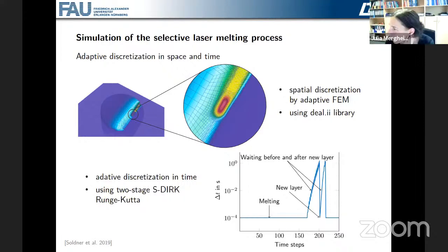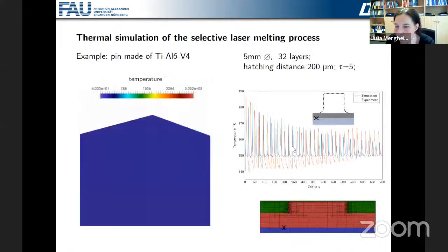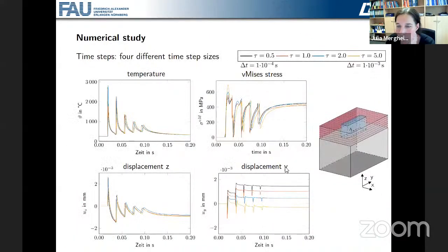Well, what we observed was that the y direction, that is the scanning direction, always showed the highest difference. In particular, let me go to the different time steps. Exactly, and that comes mainly from this line heat input. Here is the time step size, tau. We cannot increase the time step size without integrating the heat input in time. So it is not only the time step size, but also the heat input that is a bit different if we do that.